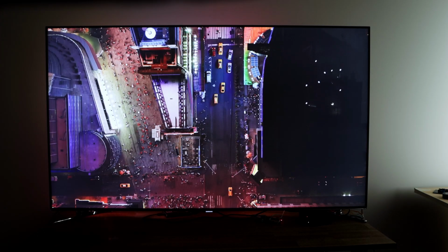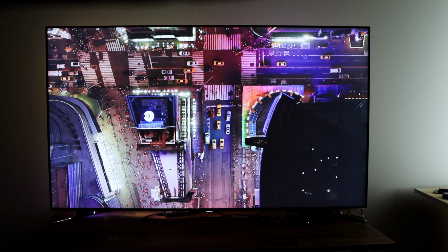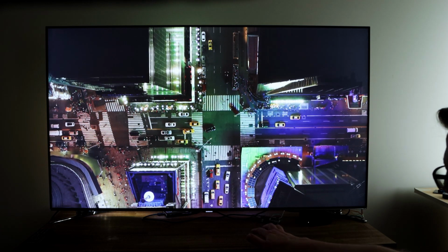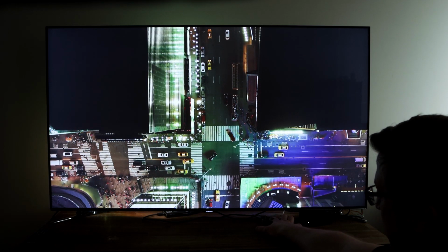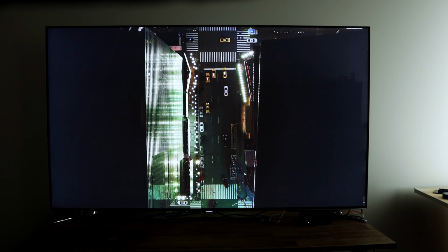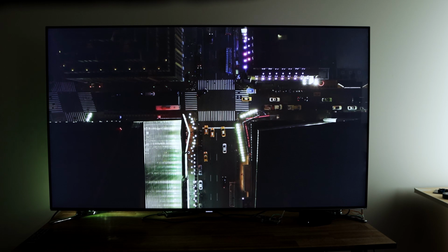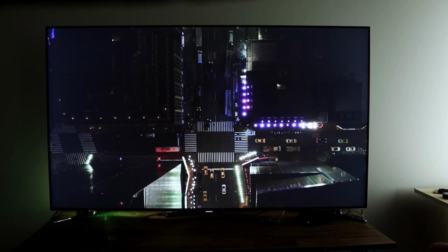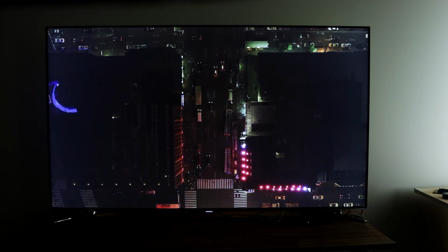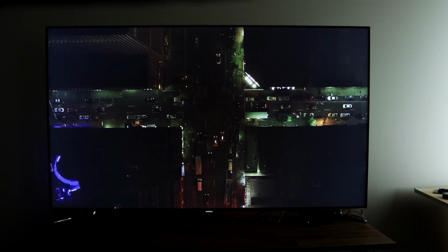Okay, so in the interest of full disclosure, it is the next day. I wasted a lot of time yesterday troubleshooting, and in the end, what actually solved my issue was I changed out the Raspberry Pi for a different Raspberry Pi. Everything else is the same. I'm connected to the same GPIO pin for the output of the LED strips, for the input of the LED strips. I did also swap the power supply. I happen to have another one of those LRS 200-5 power supplies, and I swapped it out.